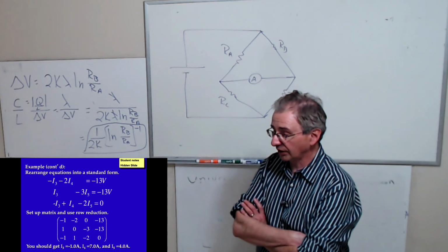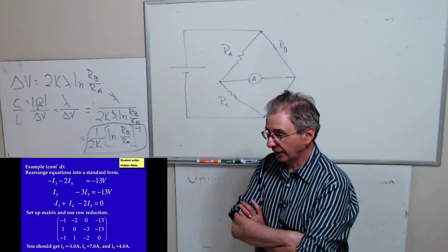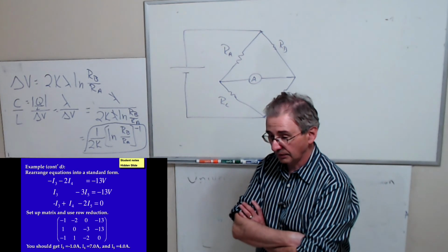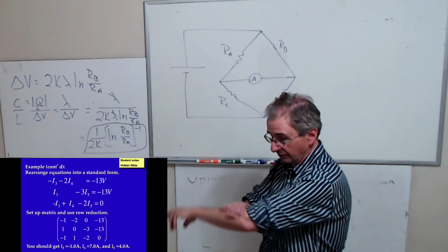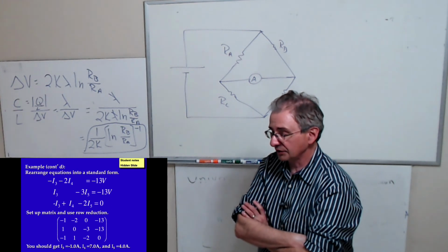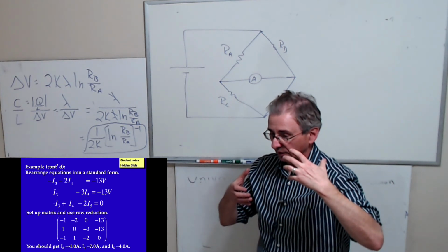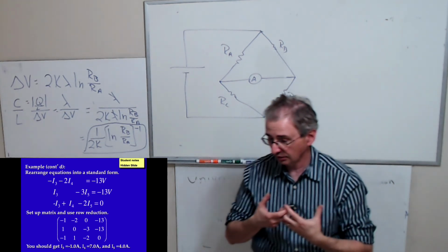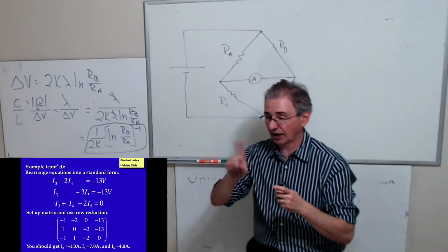In the old days, you used a galvanometer, and you put a resistor in parallel to the galvanometer to measure current. And then you put that combination in series with your circuit. When you ran the galvanometer as a voltmeter, you put a galvanometer in series with some sort of resistor, and the value you choose for the resistor is important because it's going to affect how much the galvanometer deflects.